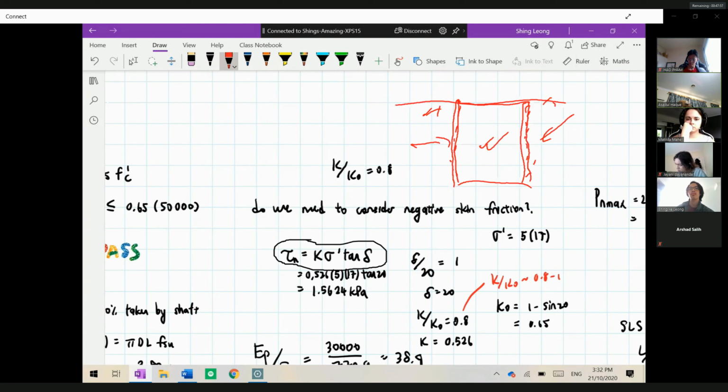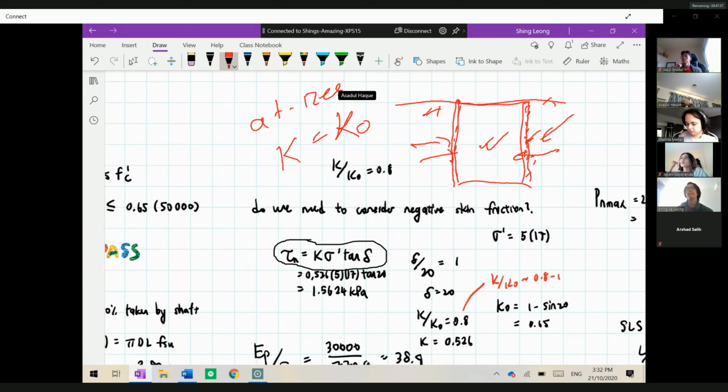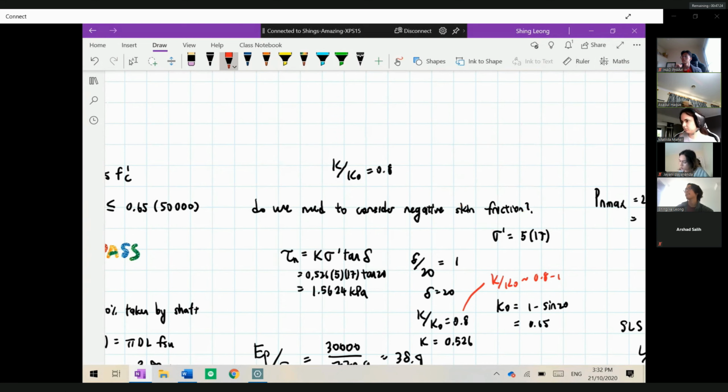So if you have got steel casing, you are pushing it down into the soft soil. That means the soil is not allowed to move towards the hole at all. So K naught condition, almost we can say, can prevail. Because soil is not allowed to move, that means at-rest condition. So now you can drill the hole through that using your rock roller, that coring bit, and slowly you can go into the rock. Now, well, that is known to you.